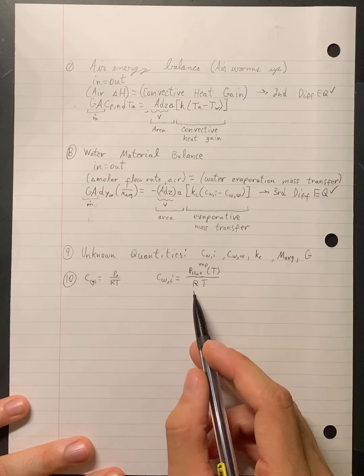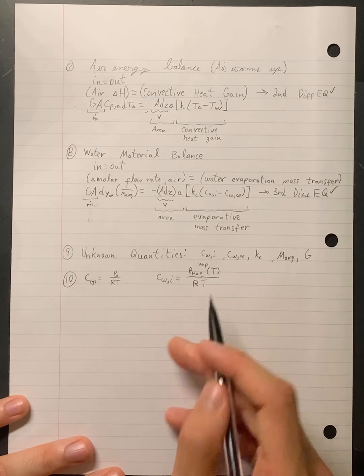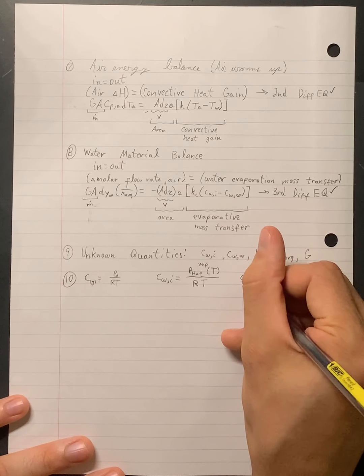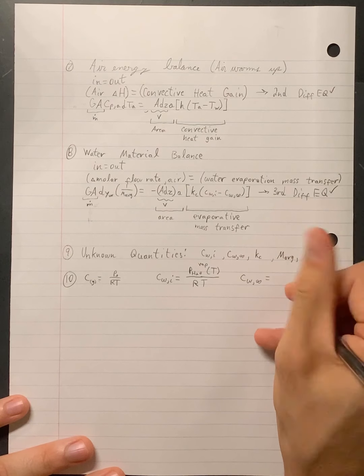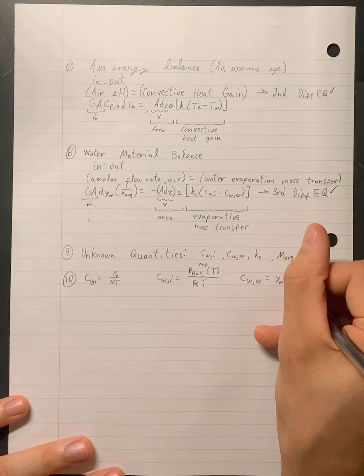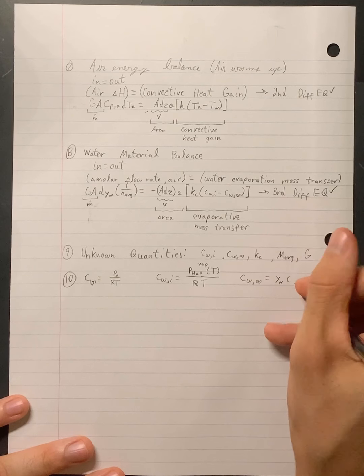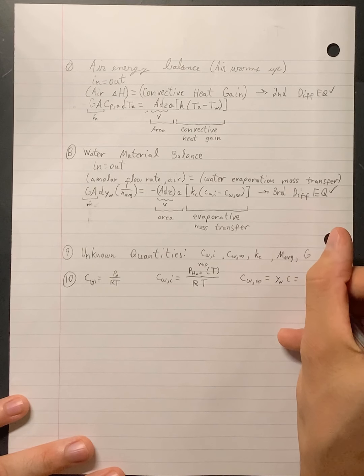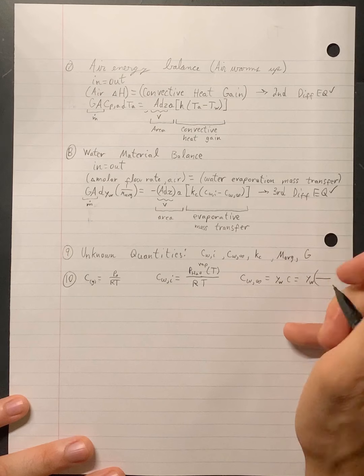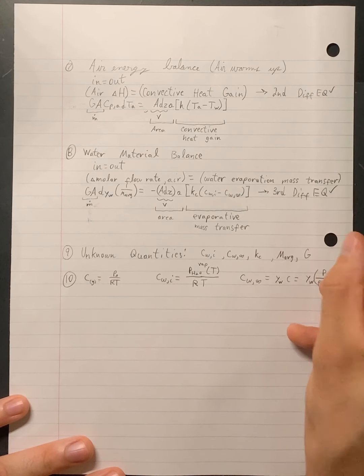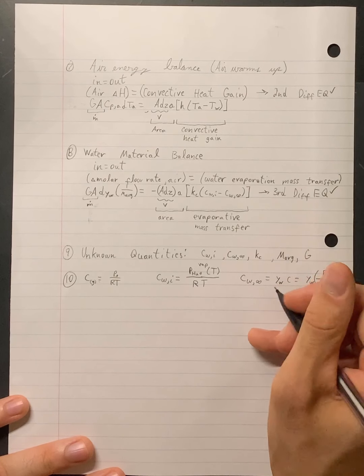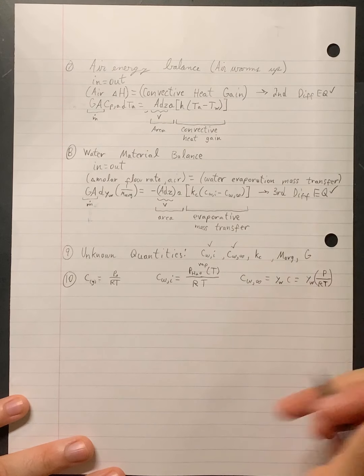We can calculate all these quantities. We might have to use the Antoine equation for the pressure here, but regardless, we can still calculate that now. The concentration of water at the bulk is simply the mole fraction of water times the overall concentration, which would be mole fraction of water times the overall pressure of that system, which is just 1 atm, or atmospheric pressure, over the ideal gas constant times the temperature of the air, which we're given. So that takes care of those two.